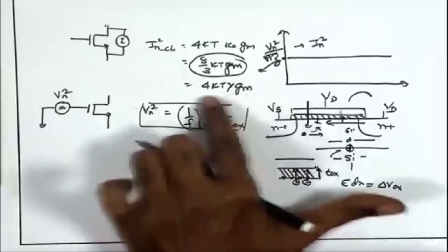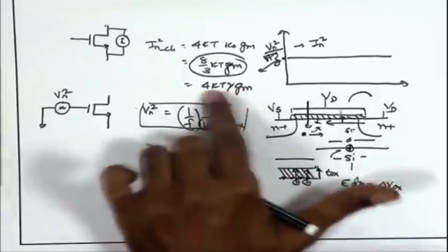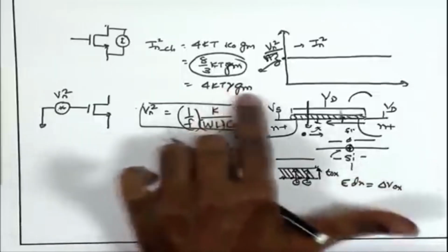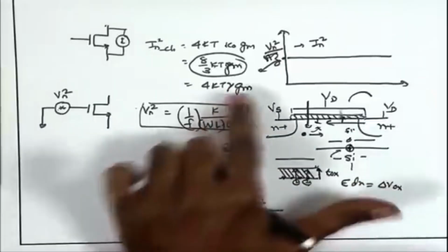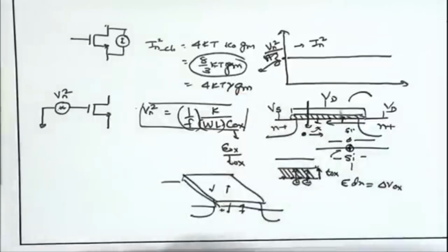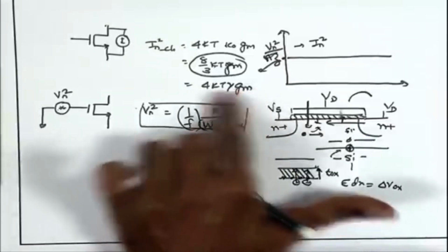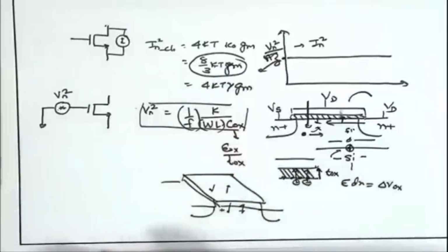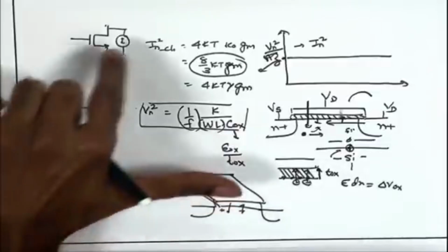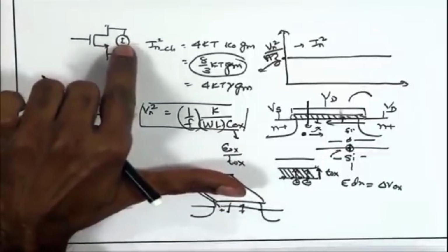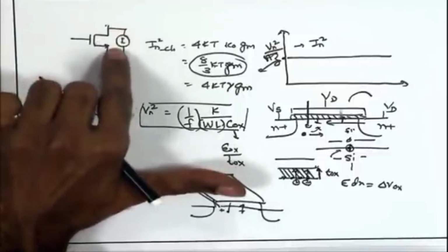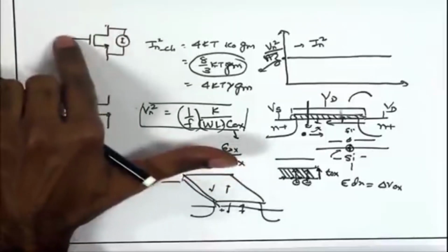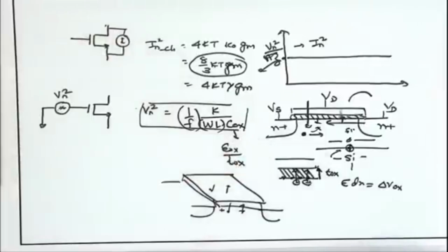Likewise, here if we look at the channel noise, it seems like larger GM is giving me larger channel current, but it may not be the right picture or may not be the most effective way of observing this noise. More effective way may be to represent or capture the effect of this channel noise current into an effective gate voltage, noise voltage.